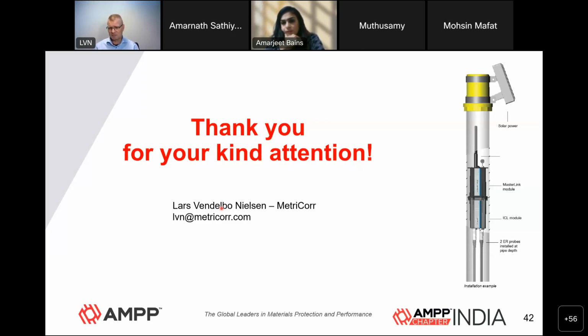So if you can document, especially under these interference conditions, by a corrosion rate probe or by a corrosion rate test station, that you are having corrosion rates less than 1 mil per year, 25 micron per year, in that case, you are actually safe.